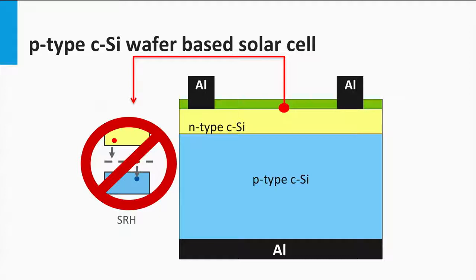Typical chemical passivation layers being used on emitter layers are silicon oxide and silicon nitride. Silicon oxide layers are formed by heating up the silicon surface in an oxygen-rich atmosphere. The surface oxidizes, resulting in a thin layer of silicon oxide. Silicon nitride can be deposited using plasma-enhanced chemical vapor deposition. We come back to that process technology when we talk about thin film PV technologies.